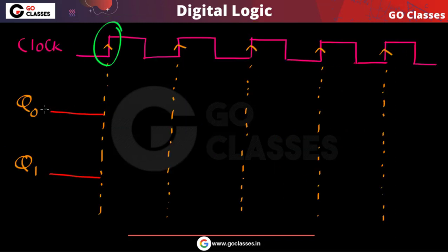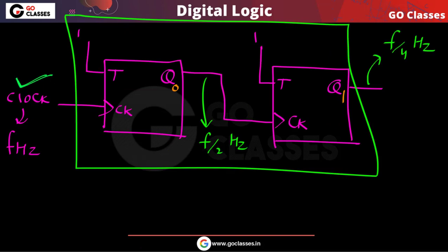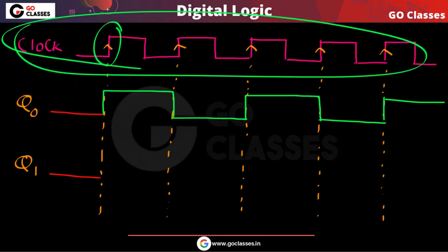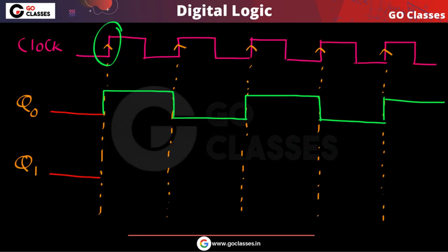So initially q0 is 0, and with every rising edge, q0 will toggle. You can notice that for the first flip-flop we have applied the input clock. This input clock is operating the first flip-flop, and the T input is 1. So with every clock pulse, with every rising edge, the output of this flip-flop, q0, will toggle.